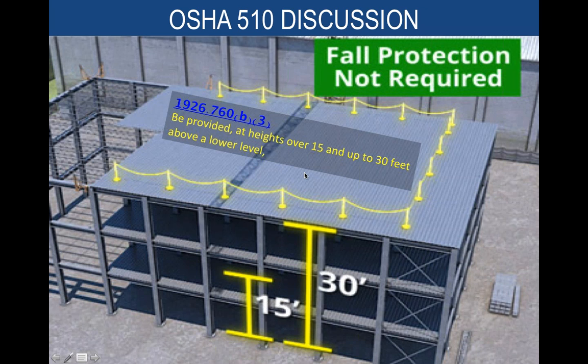Okay, so that's basically what the controlled deck zone is telling us at the bottom of page 3 on module 6. Moving on to page 4 now. A controlled deck zone, or CDZ, is a substitute for fall protection, right, where decking is initially being installed. Only workers trained for CDZs are allowed to work in that area. So it would only be roofers or whoever's doing the decking work. The controlled deck zone has to be clearly marked, and the zones can be no wider than 90 feet, and 90 feet deep from any leading edge. So the full width is going to be 90 feet, or depth.